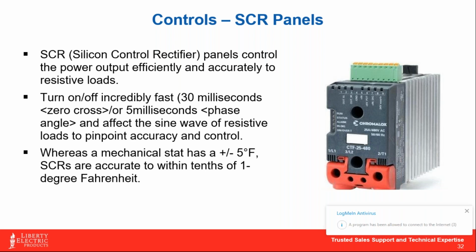By pulsing that power on at a lower rate and bringing it up to temp, we can literally double, if not triple, the life of the element just by reducing that initial shock when they come on.